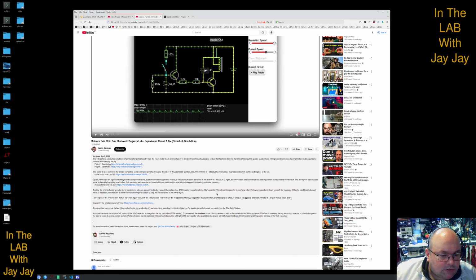The simulation stores only the last 10 seconds of audio on a rolling basis, and no audio is played during the simulation run. To play the simulated output, you must press the play audio button. Note that the circuit starts in the off state until the 10 microfarad capacitor is charged via the key and 100k resistor.